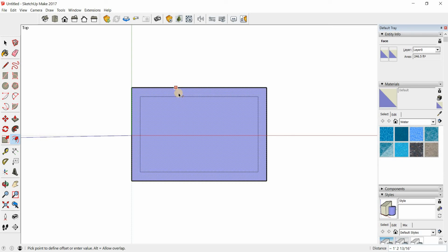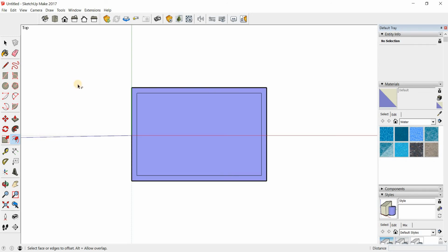When you do this, you also see on the bottom right hand corner of your screen the numbers are changing, and the number that we want is about 9 inches to get a 9 inch thick wall. So 9 quotation mark, and then press enter, and then you have your walls, right? If you take a look at your floor plan that I've provided, there is another wall somewhere around here, and there is a precise dimension that we need to work with as well.